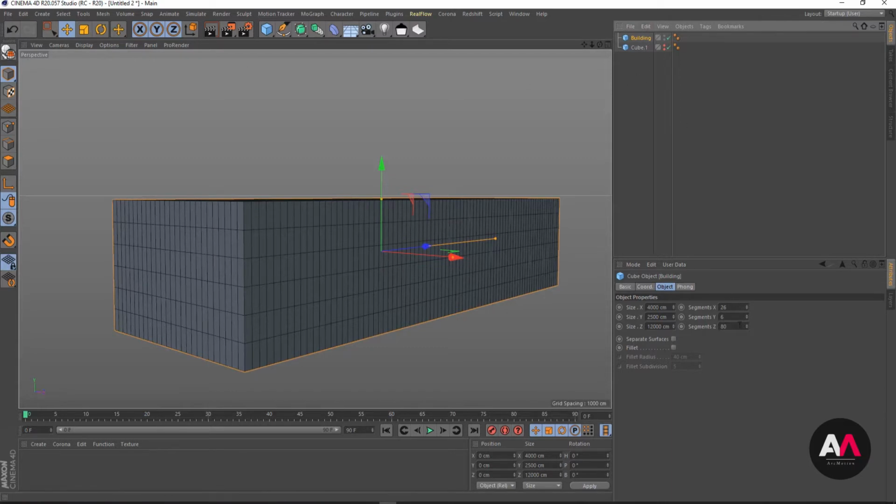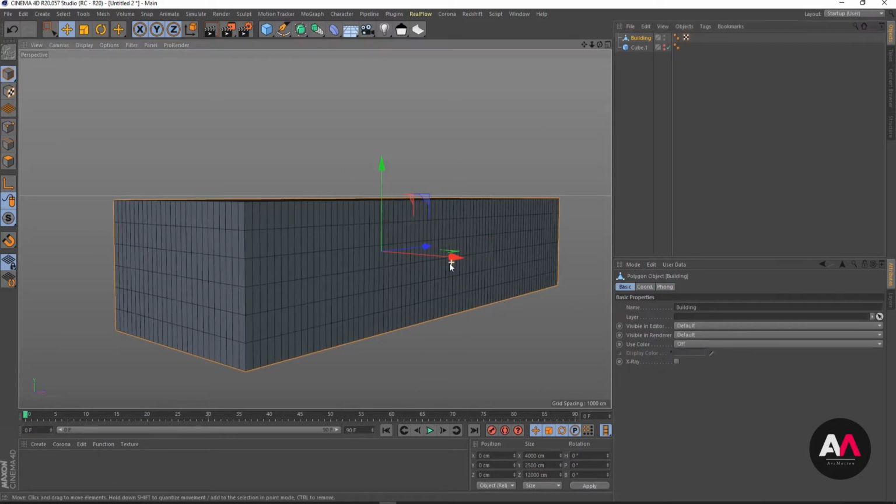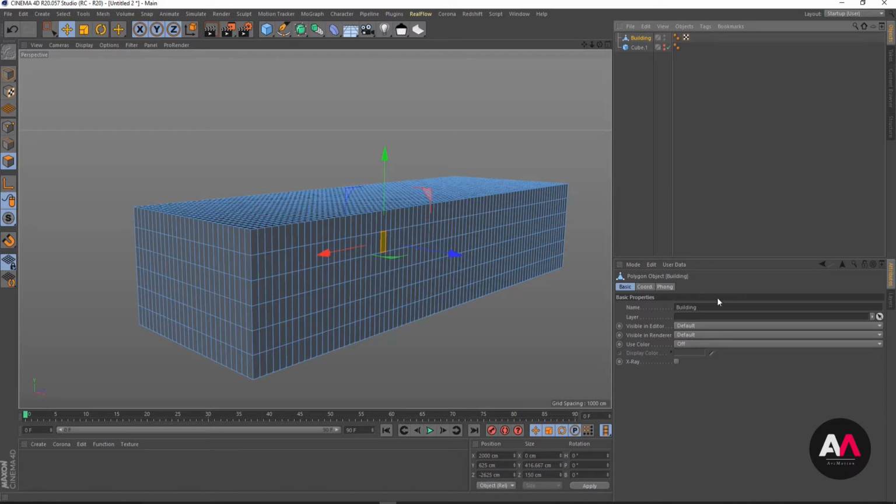When I do that, we don't have access to the parameters we had before, but instead we have access to this volume as a polygonal object, made of points, or lines, or faces, or polygons. But as you see here, I don't have access to the parameters we had before. This is why I saved one parametric version of the object, in case something goes wrong. So we have access to the original parameters and we can change and make a new one if we want.